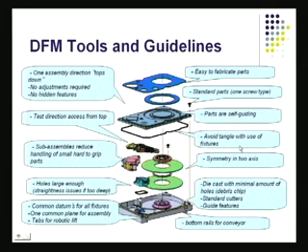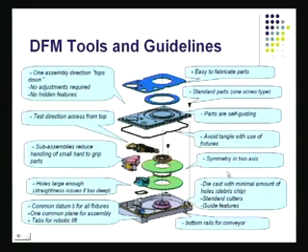Avoid tangle with the use of fixtures. This happens a lot when you've got wire harnesses and so on. You've got to make sure things are easy to fit, easy to isolate, and so forth. That is done a lot when you're trying to, for example, put together a motorcycle. At the design stage itself, they try to figure out how it is going to be put together, and then they try to make sure it's going to be easy for the person who is going to be doing this. And the same thing would apply for an electronic device such as this drive.